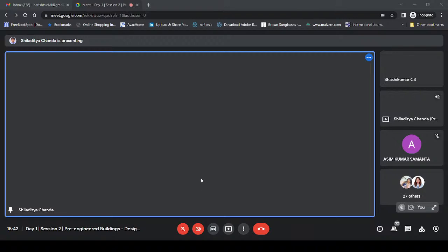But for say 1400, whatever your purlin spacings are. Sir, and is the rocker a must? No, sir. Rockers or flange bases are not a must. I have not used that for say 6 meter, 6.7, up to 7.5 meter. But if it is more than that, sometimes we need to use that.